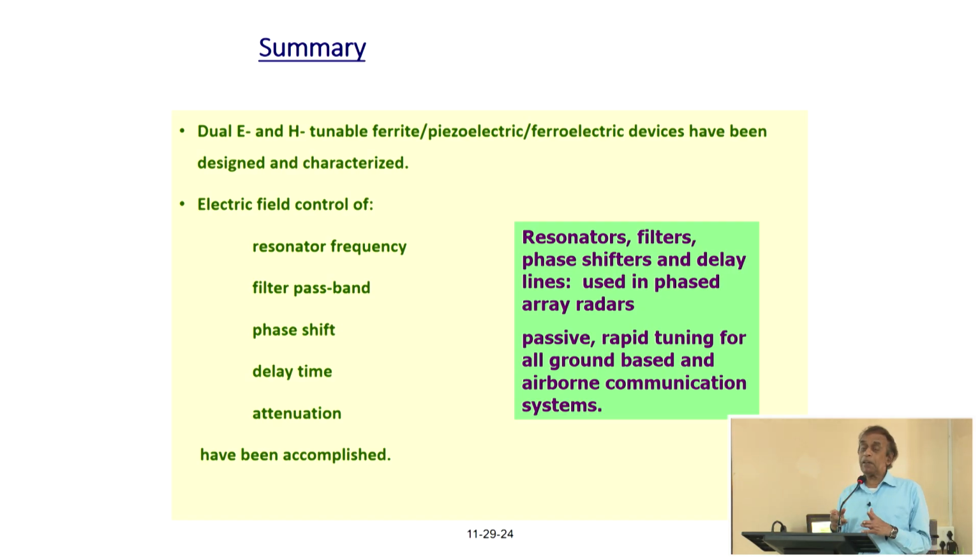But with a permanent magnet, the field that you apply to the film is non-uniform. That can lead to a spread in the FMR profile. So instead of 1 Oersted for the linewidth, you may get 10 Oersted because of the non-uniform magnetic field. But if you can live with it, then you don't need any PZT or any voltage source. All you have to do is tune the magnet mechanically.